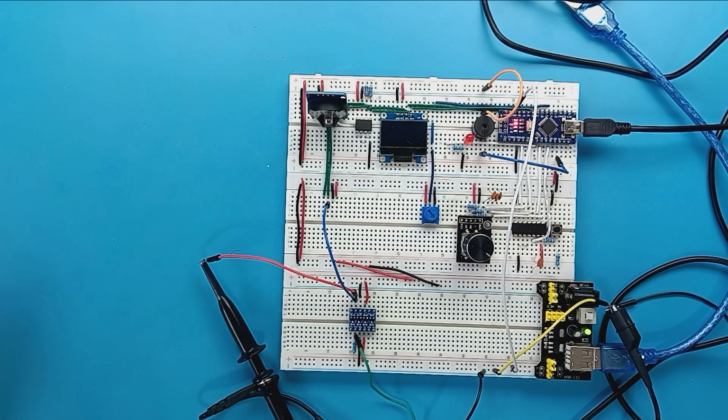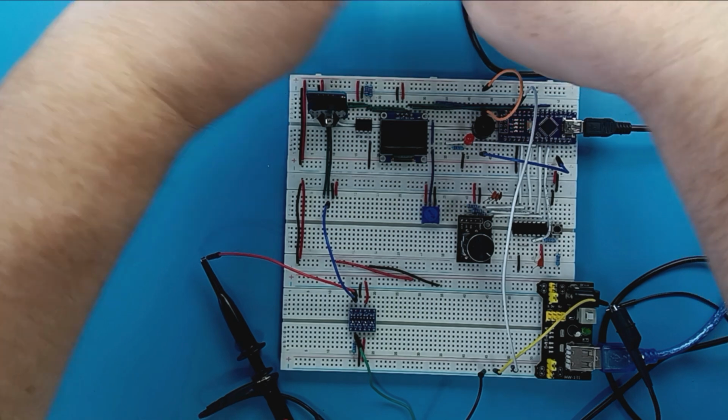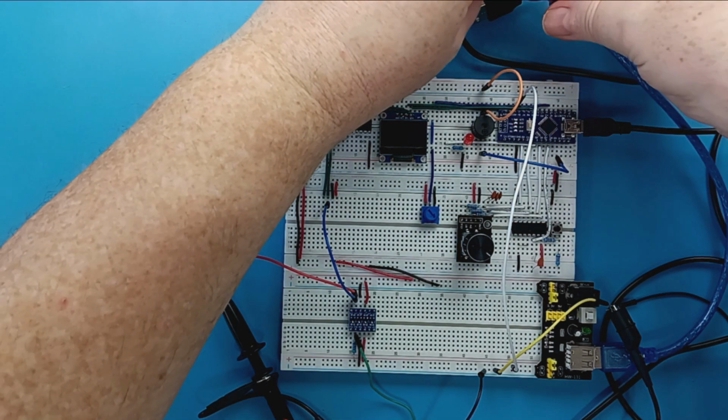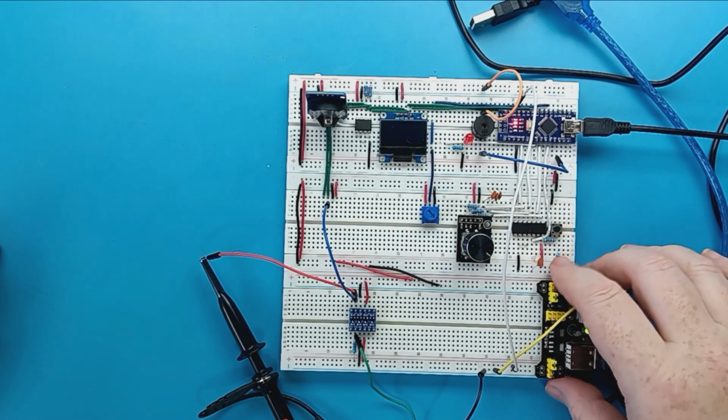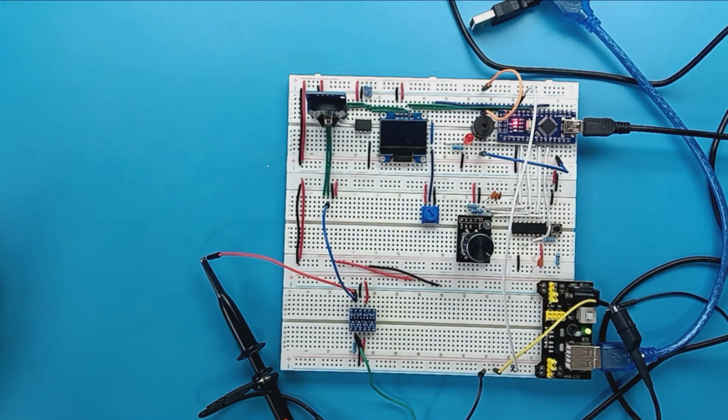Tools, upload. Okay. So again, uploading code works a lot better when you connect the microcontroller. I just don't like having the microcontroller powered as well as an external power source. And the sketch is done. It's uploaded. So we've now changed the I2C bus to 400 kilohertz. So let's power up. So we're now powered.